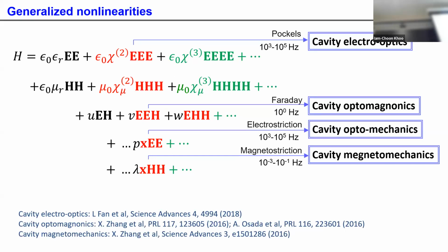I'm interested in the wavelength version of microwave to optical. Right now, what's the current rate? Oh yeah. Right now we are mostly interested in the superconducting qubit frequencies, from about 3 gigahertz to 10 or 11 gigahertz. There was a recent work from Stanford and Chicago that did 110 gigahertz. It was a very expensive setup, also power hungry. For practical reasons, we are working on 10 gigahertz rather than 110 gigahertz.